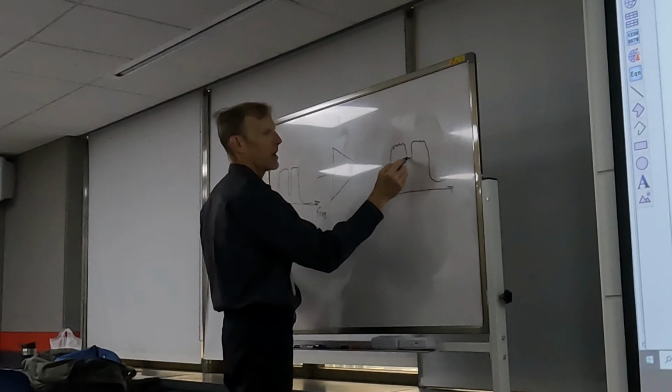I'm applying the same test signal with this notch, and I'm calculating the power in the notch, doing an average over the spectrum, and also calculating the power outside the notch. And I take the ratio. The ratio of the input signal notch is roughly minus 86, and the NPR gradually gets worse. Basically, the notch fills up, and this is the output power.